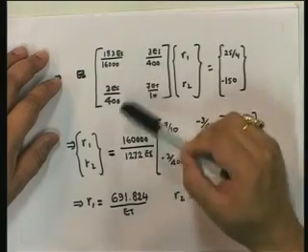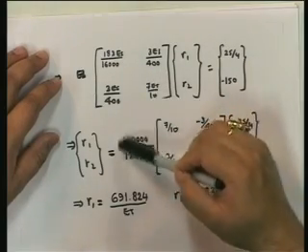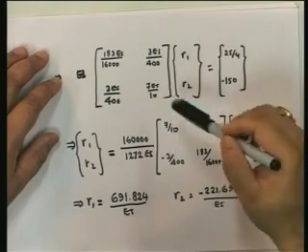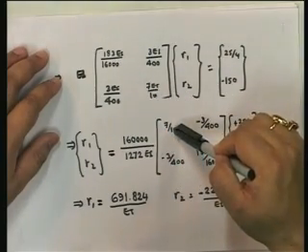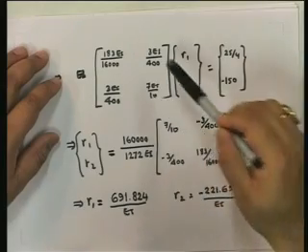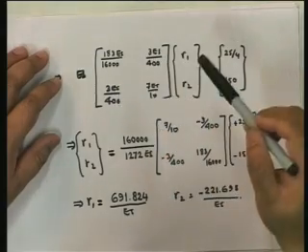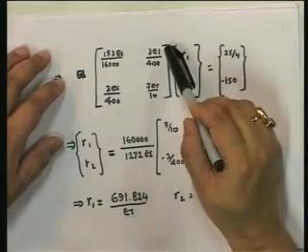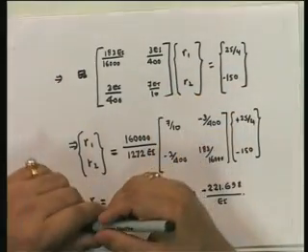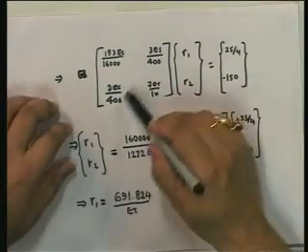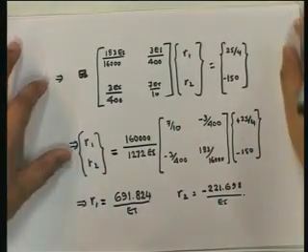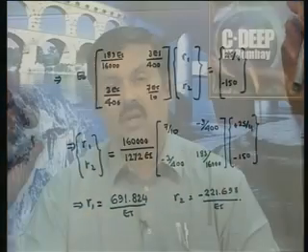The determinant of this is 1272 EI upon 160,000. So inverse is this, and then the cofactor of this is this. The cofactor of this is this. The cofactor of this is the minus of this. The cofactor of this is the minus of this. Note something. Again, like last time I had said that this matrix is symmetric. Again you see that it is symmetric. The reason for it to be symmetric is, understand what this is. This is the force at a particular point that gives the displacement at another point.